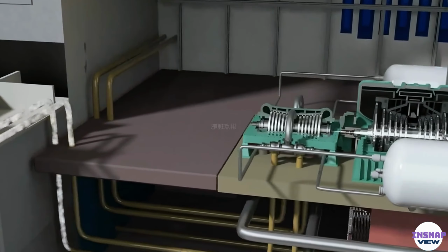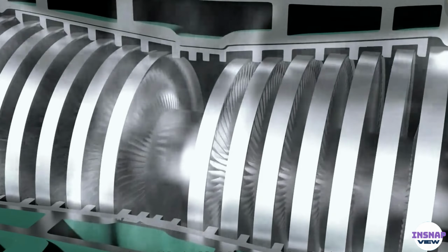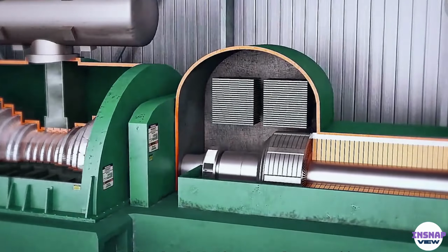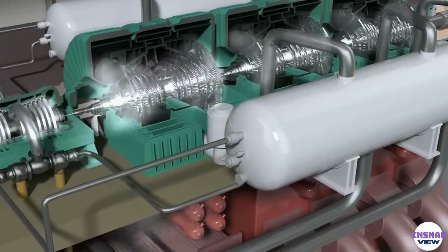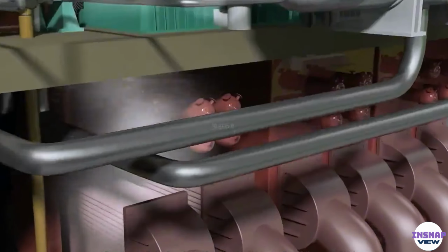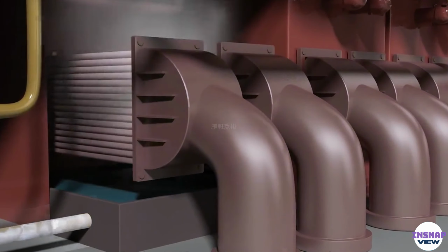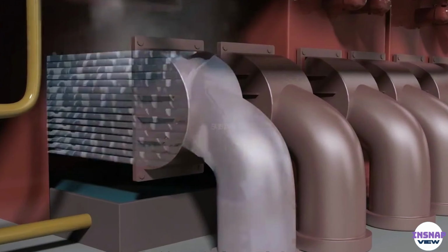The process that follows is basically the same as thermal power generation. Steam enters the turbine through pipes. The blades of the turbine are propelled to turn by steam, converting thermal energy into mechanical energy, and further drives the generator to generate electricity. Then, after passing through the low-temperature end of the turbine, the steam is cooled through the condenser and becomes liquid water again, and then it's pumped back to the steam generator.